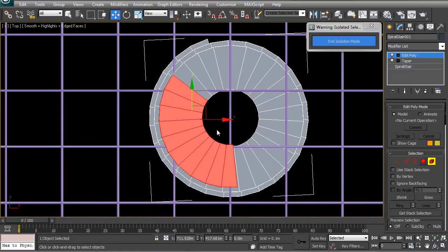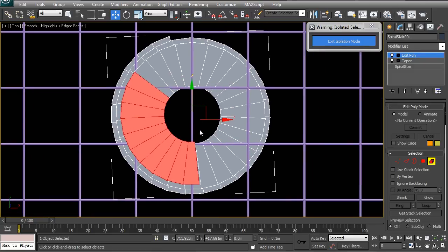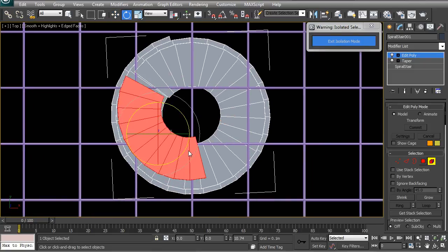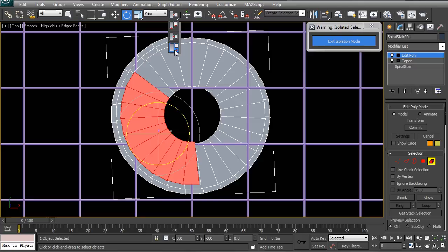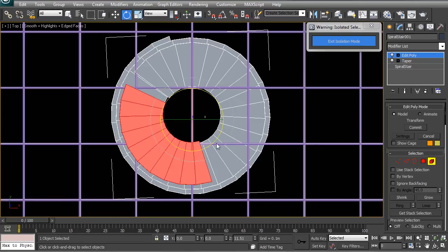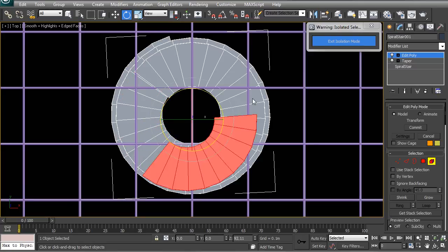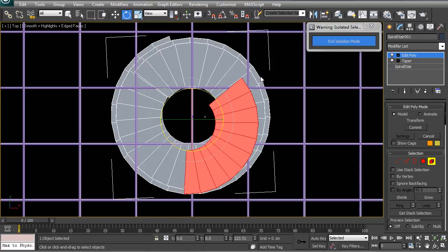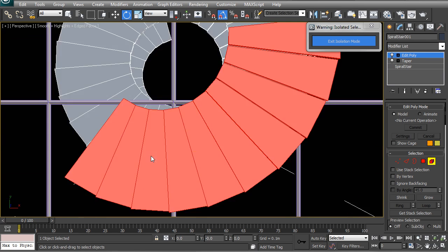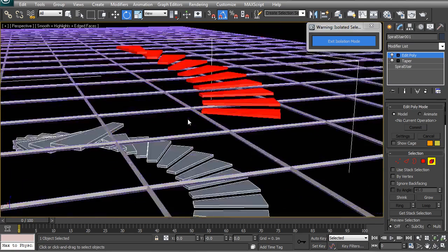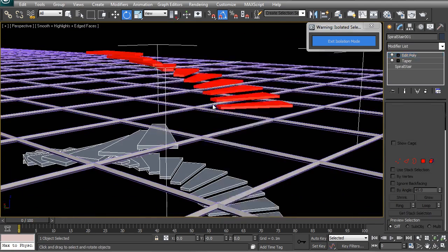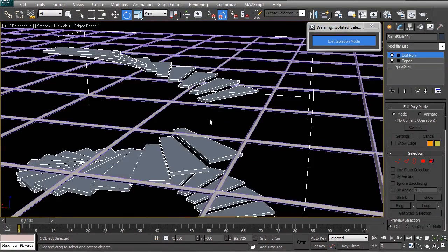And then once you go and basically rotate it, you will be able to rotate it around the center, being the point that is in the center of the spiral stair. So I'm going to move it now by about 90 degrees. Let's turn on my angle snap by pressing A, and I'm going to have a 90-degree difference there. So what I've basically created is this space for myself, and I can now create a landing platform here.